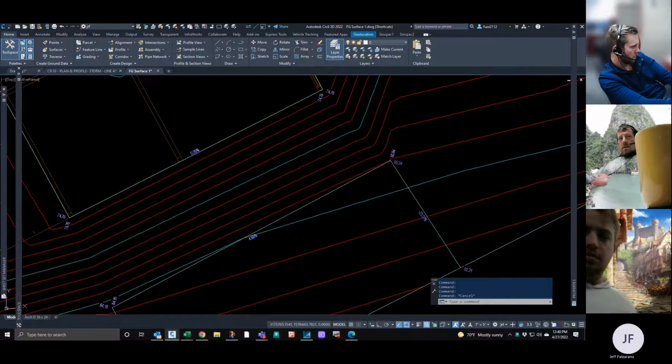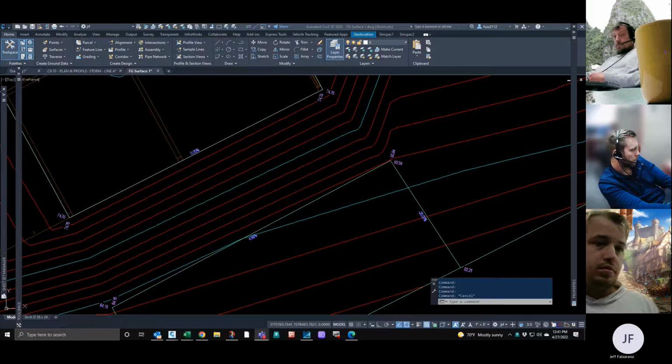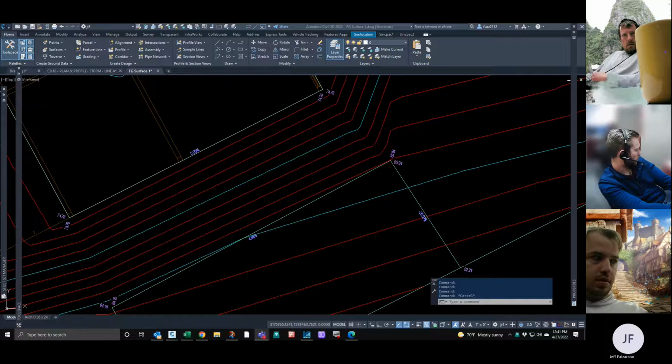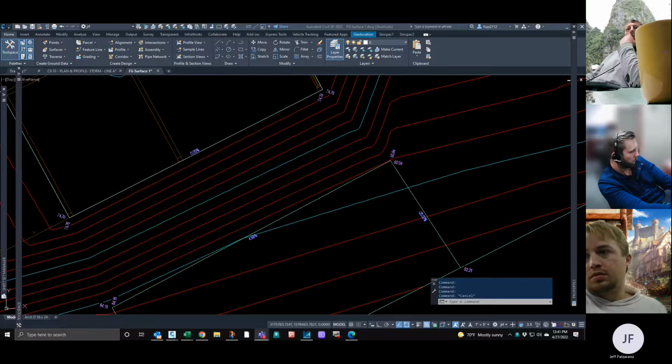What's the difference? I mean, how much can you retain, Jeff, before you have to tier the walls? It depends on the city. It depends. We don't really get into that much. The structural engineer will usually dictate that, and we usually don't detail that. I mean, if it's a 20-foot wall, then yeah, we'll have to. But if it's like a 5, 6, or 7-foot wall, we just draw it at a foot thick and then draw the top and the bottom, and then we're done with it.